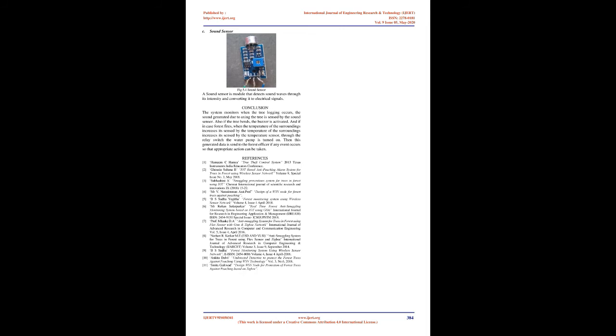Module 5: Relay switch. High voltage electronic devices can be controlled using relays. A relay is a switch which is electrically operated by an electromagnet. The electromagnet gets activated with a low voltage, for example 5 volts from a microcontroller, and it pulls a contact to make or break a high voltage circuit. One of the most useful things you can do with an Arduino is controlling higher voltage, 120-240V devices like fans, lights, heaters, and other household appliances.